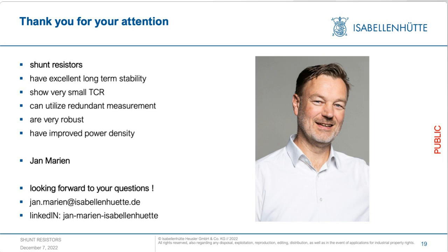And the same is true also for busbar designs. Here you have to ensure a good heat conduction from the device into the busbar, so a good connection between the shunt and the busbar and an overall thermal design. I hope this answers this question.